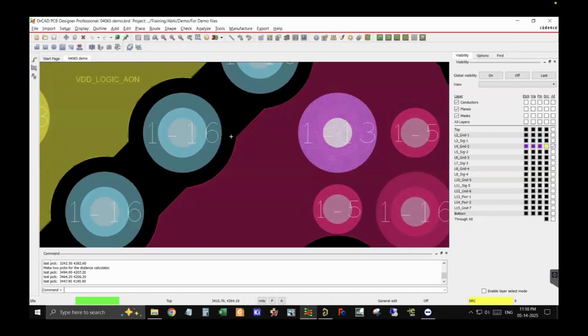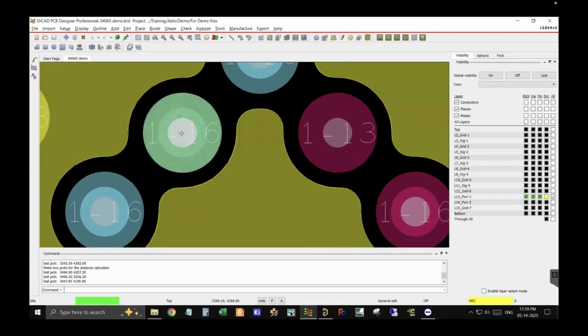The pad size has increased because on layer 4 there is a buried mechanical drill, which is a 6 mil hole and 4 mil annular ring, which is a 14 mil pad. So we used layer 1 to 2, 2 to 3, 3 to 4 blind and buried wires, the laser drill, and then 4 to 13 is a mechanical drill, which is 6 mil hole minimum.